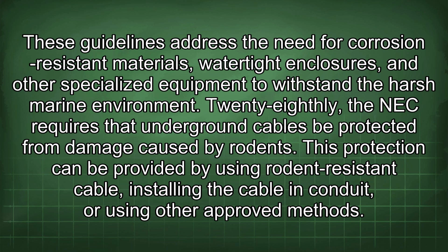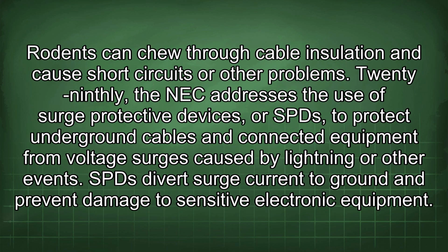28thly, the NEC requires that underground cables be protected from damage caused by rodents. This protection can be provided by using rodent-resistant cable, installing the cable in conduit, or using other approved methods. Rodents can chew through cable insulation and cause short circuits or other problems.